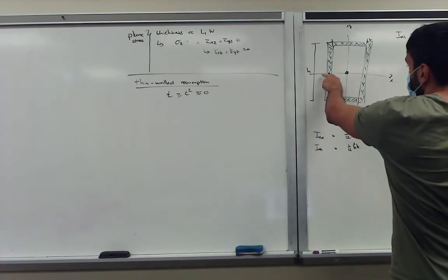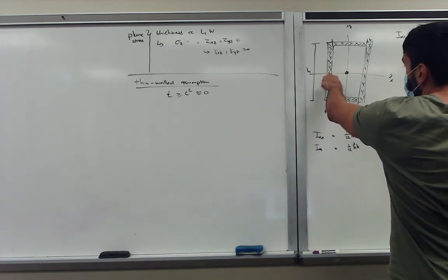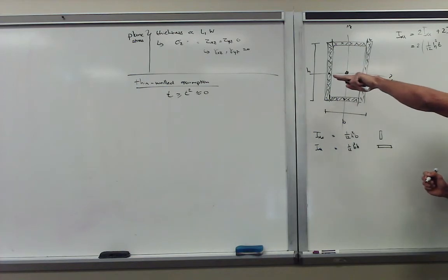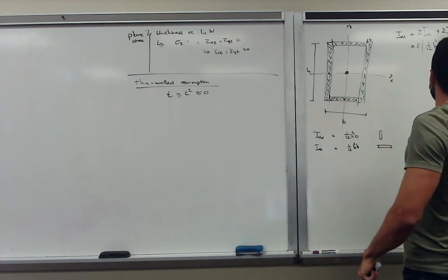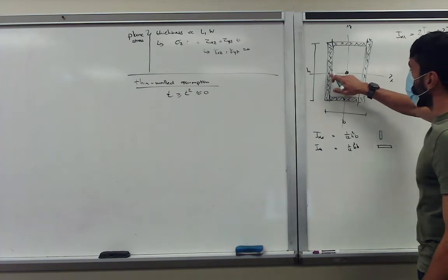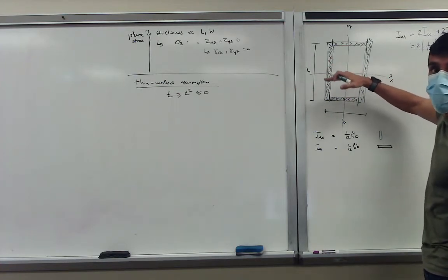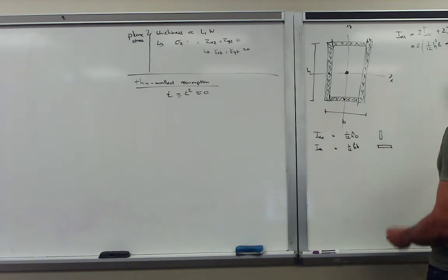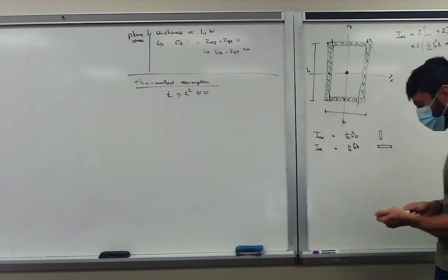So of course, this is the moment of inertia around this axis system. So it technically is aligned with the centroidal axis system, so they coincide. So basically, yes, in theory you will have an AD term, which is h times t, but then the difference between the axis, the parallel axis, the d term is equal to 0. So that's 0 squared. Let's just put that in there anyways.